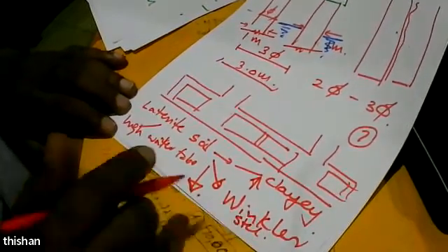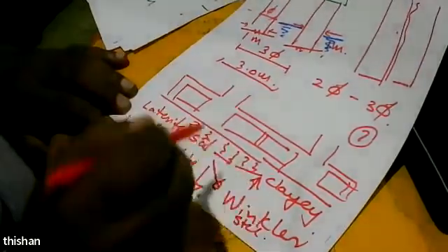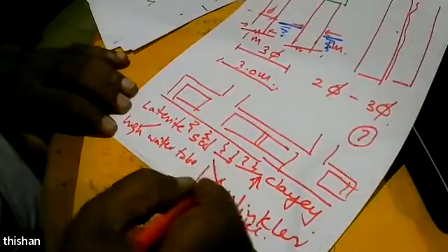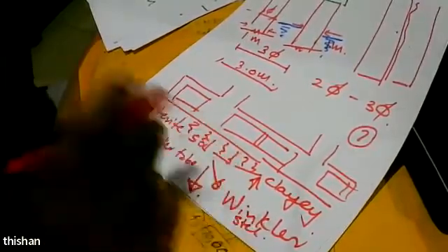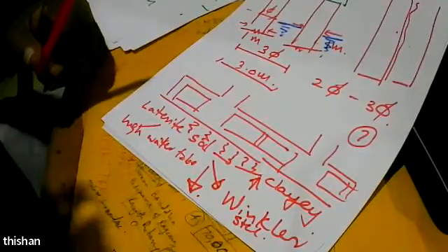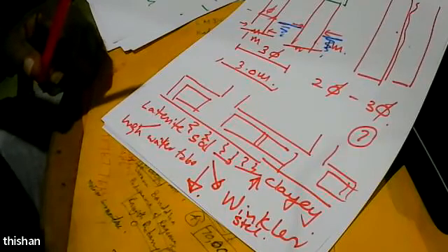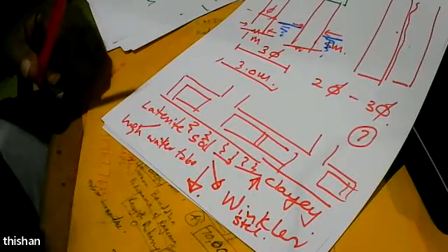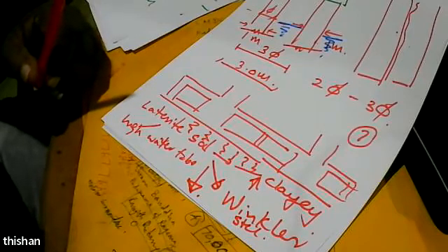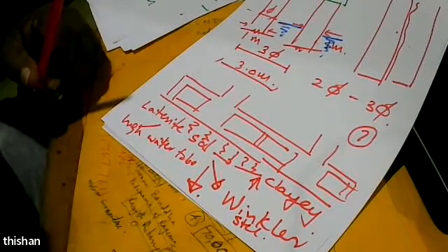So if it is a strong soil, we go with sandy soil, we consider it as sandy. And whatever is low, then you'll find the laterite soil behaves more like sandy soil. When it is saturated, the laterite soils behave more like a clay soil. So depending on the depth to the water table, the top of the water table, you have to make your own decision.